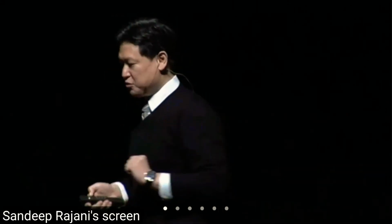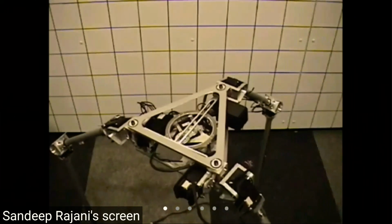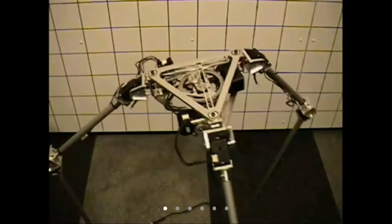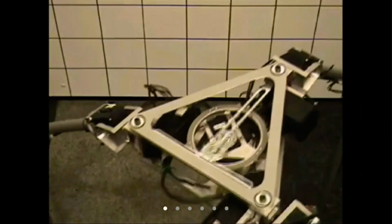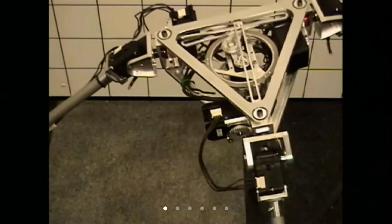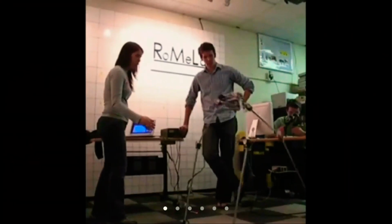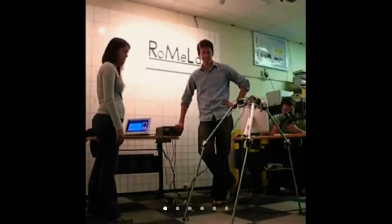So we have 2 prototypes. The first version in the back, that's Strider 1. The one in the front, the smaller one, is Strider 2. The problem that we had with Strider 1 is it was just too heavy in the body. We had so many motors, aligning the joints and those kinds of things. So we decided to synthesize a mechanical mechanism so we can get rid of all the motors, and with a single motor, we can coordinate all the motions. So it's a mechanical solution to a problem instead of using mechatronics. With this, now the top body is light enough, so it's walking in our lab. This was a very first successful step. It's still not perfected. It constantly falls down, so we still have a lot of work to do.